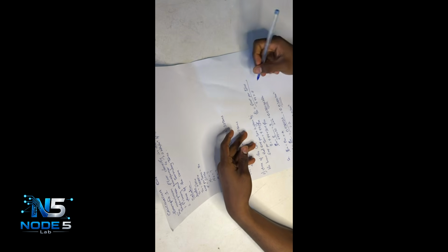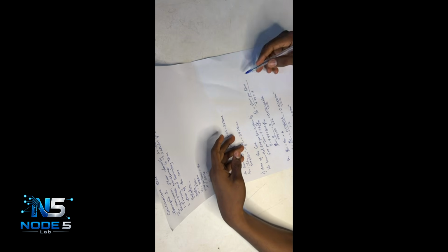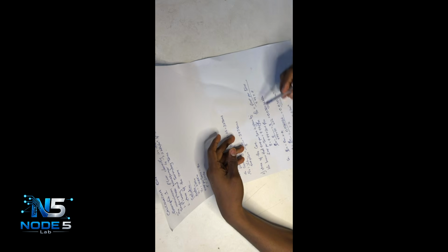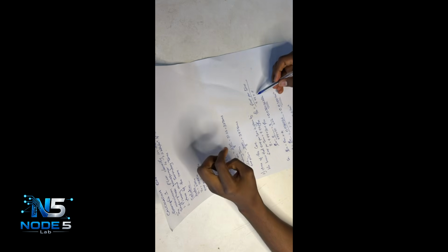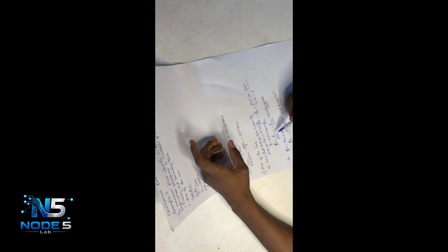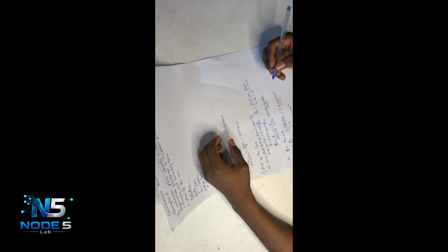So you put in the values. The EMF per turn is 8. The 4.44 is a constant, then times the frequency f, which is 50. That will give you 0.036036 Webers. That's the flux. Now that we have the flux,